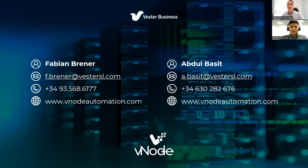And what is this capability, store and forward? Can you please explain a little? Yes, totally. We have two levels of store and forward. So let's imagine we have a vNode collecting the data in the control network. Then it's pushing the data from the inside to the outside to another vNode in the IT network. And this vNode in the IT network, using MQTT, is pushing the data to the cloud.